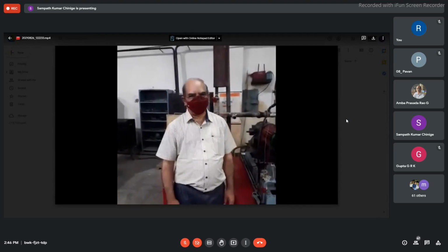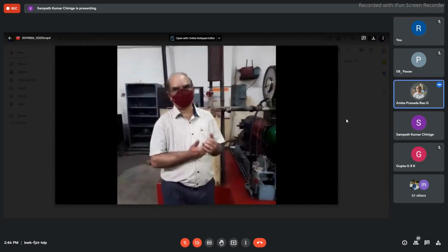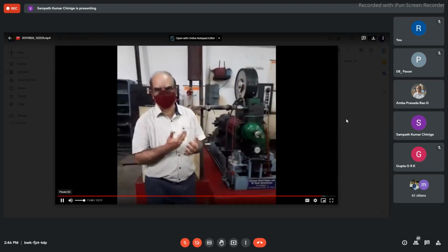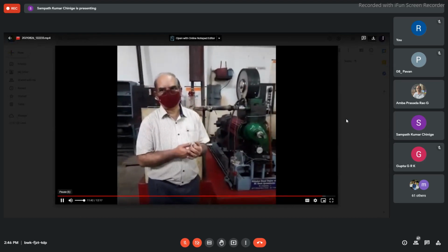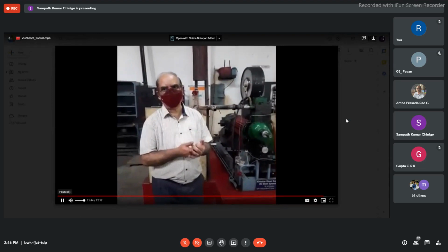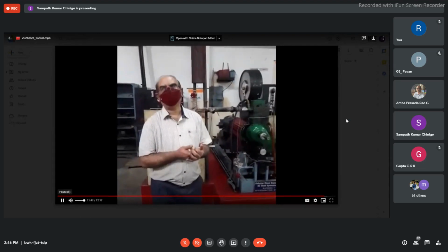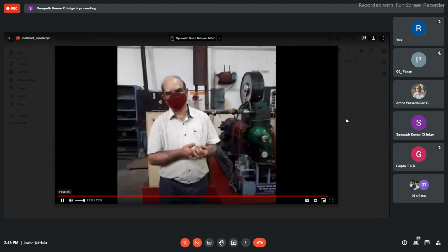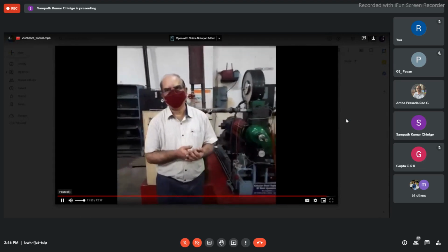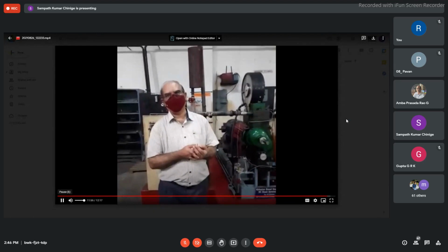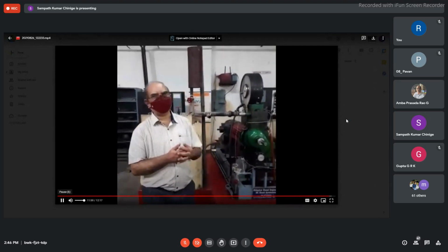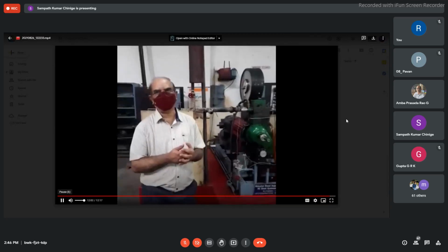Drawing fuel consumption versus brake power, the procedure will be explained as detailed below. This will help us to approximately calculate the friction power. This is the approximate method of arriving at the friction power of an engine at a given speed of an unthrottled engine. This is a diesel engine, which is commonly called an unthrottled diesel engine.